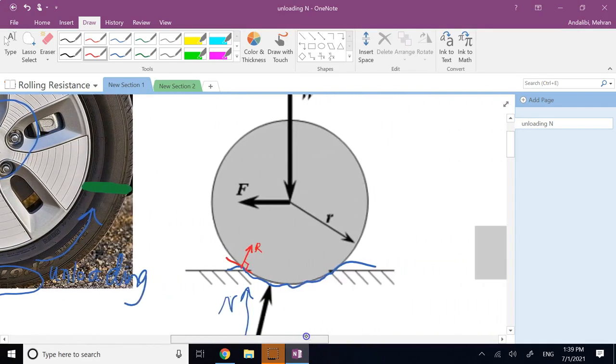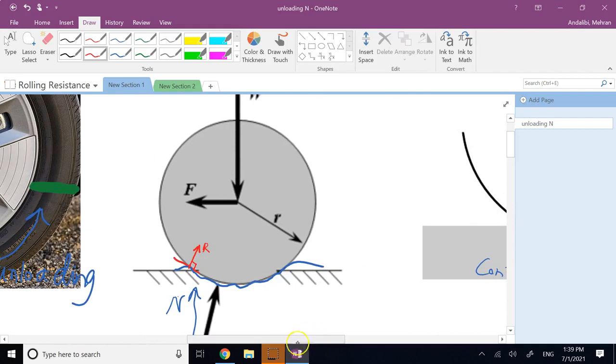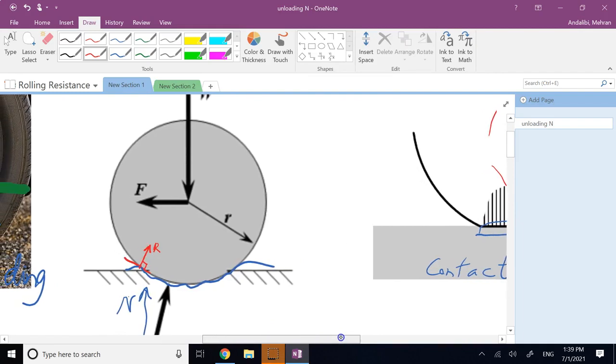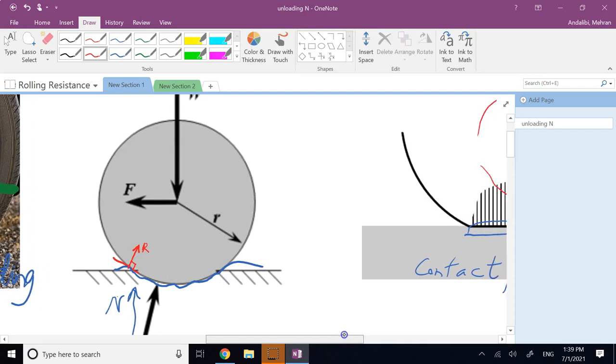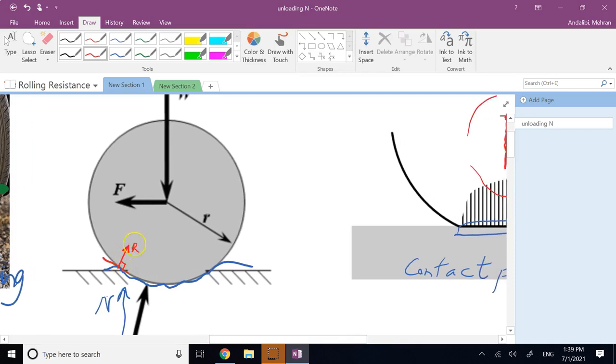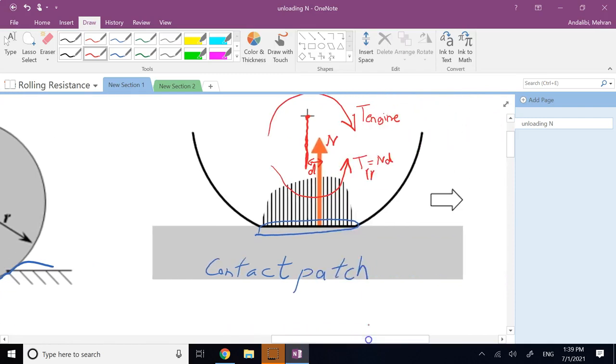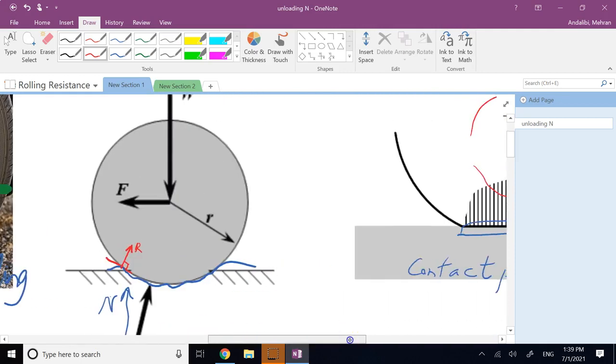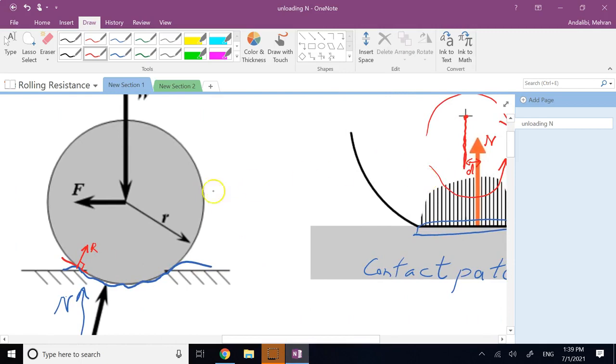So what basically can explain the rolling resistance for a steel wheel on a steel rail is really this backward component of the normal force or this opposite torque, not the hysteresis. Okay, but for pneumatic tires, it's really the combination. So it's either one of these, because these two are equivalent. You can either use this one or this one. These two are equivalent, not two complementary mechanisms.